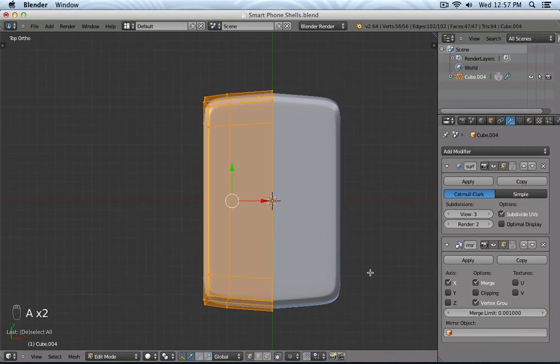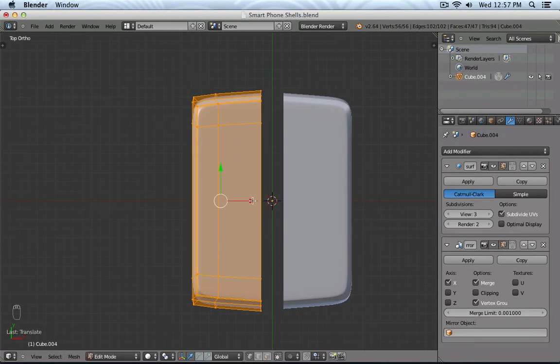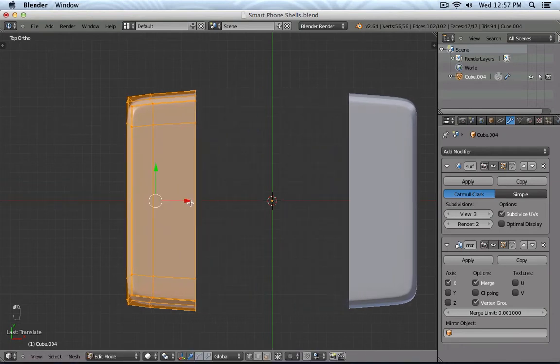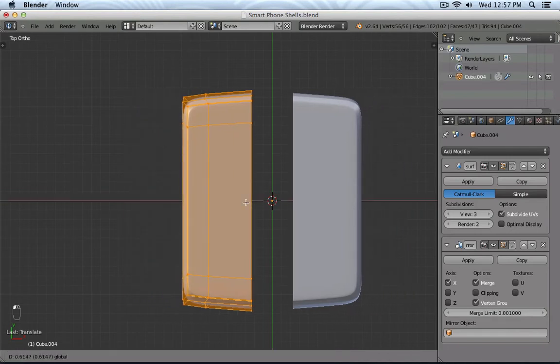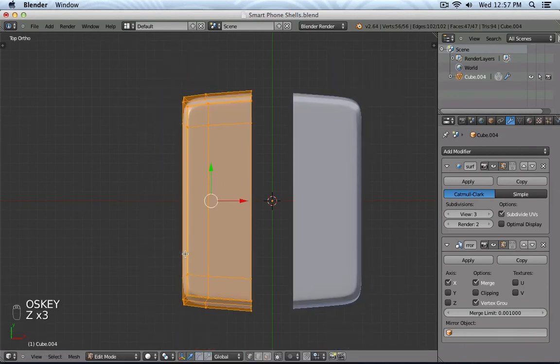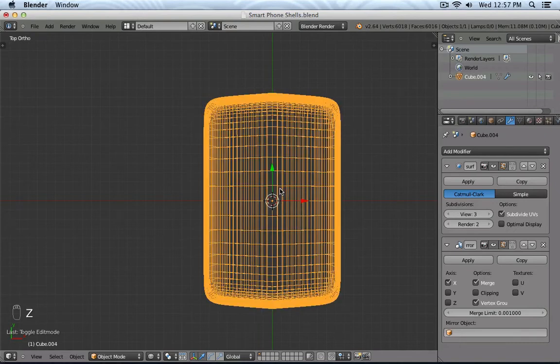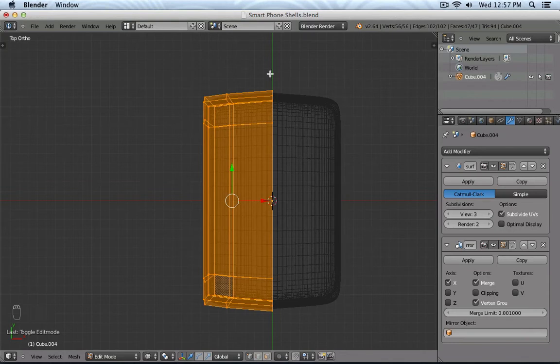And if I select my model and, for example, move everything to the left, you can see actually that there is now a small gap. So the further the object is to the left, away from the object center, the same distance then my interactive mirrored object or clone is being moved away to the opposite direction. So you see, same also applies for all the stuff. So let me undo this. So to, of course, have a perfect match along the mirror line, it is imperative that your object center is perfectly lined up with the mirror axis geometry.